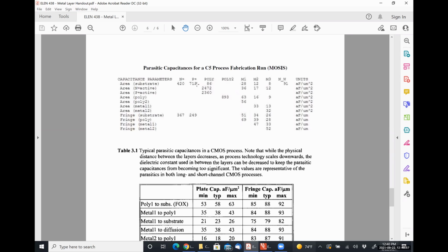Those guys are ludicrously high because effectively the capacitance is formed with the depletion region being the insulator material between it, which is going to be very, very, very thin. And those guys depend on the voltage and all that kind of stuff. The polysilicon layer is the largest intentional capacitance that we can get with the substrate because it's the one that's physically closest.